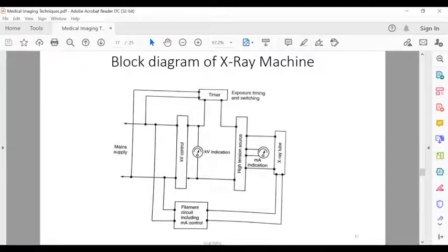Before coming to the actual exposure, the film materials must have been kept in the dark room during the past 12 hours. This is considered the best preparation. The adaptation to a new temperature is quite fast and occurs within a few minutes. It can take several hours for a film to get dimensionally stabilized after a change in relative humidity. Then the hermetically sealed film package is usually stored in a refrigerator.